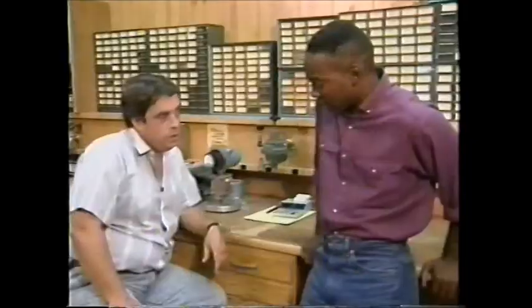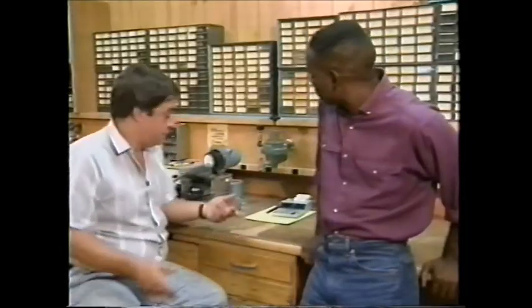Yeah. Now, the level in the number 6 feeder tank is 13.5 feet. Now, if I wanted to know how many gallons were in the tank, how would I calculate? You'd have to calculate the volume in the tank by taking the formula for the volume of a cylinder and substituting the diameter of the feed tank and the height of the fluid. Then you'd solve the formula and convert the answer to gallons. It's pretty easy to do. Here, let me show you.